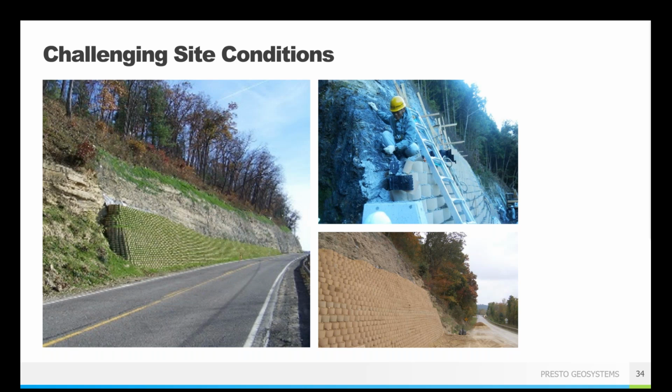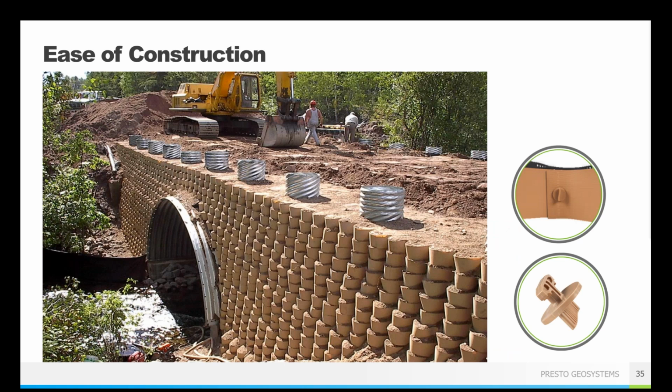All right, ease of construction is great. If you do have existing structures, in this case, there was a large culvert that they needed to build around. We've had lots of contractors come back and say, I'd never used this before, but it was actually really easy to install. Again, you don't need heavy equipment to install any of this stuff. You don't have to lift it by crane or anything. Usually the biggest equipment is an excavator, and that's to put the soil or the stone in place so that you don't have to do it all by hand. So very easy to install.